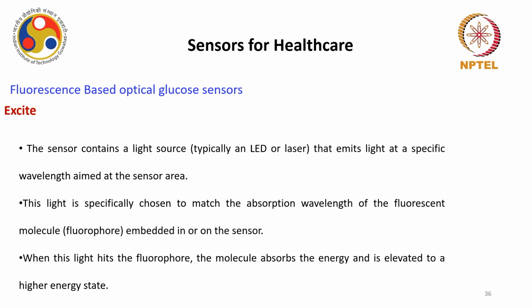Fluorescence sensors, like other optical sensors, contain a light source. We have seen that mostly it is based on LEDs or laser. This source emits light at a specific wavelength which is aimed at the sensor's surface area. This light is specifically chosen to match the absorption wavelength of the fluorescent molecule, which is known as fluorophore. We will be using this word regularly. Please note that this is nothing but a fluorescent molecule embedded on the sensor.